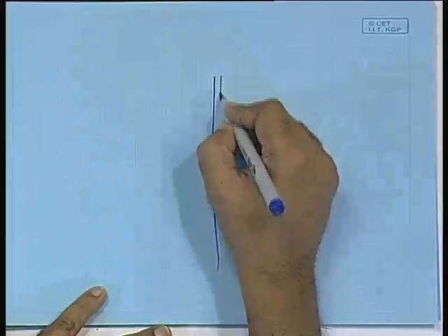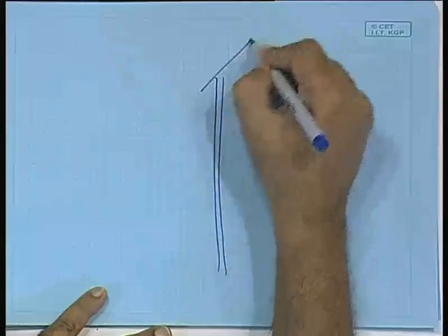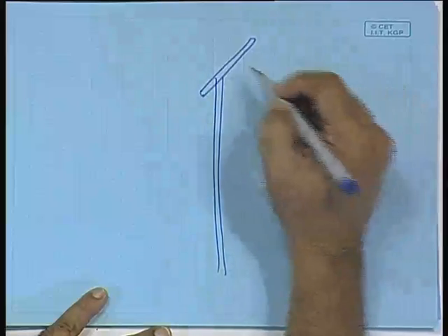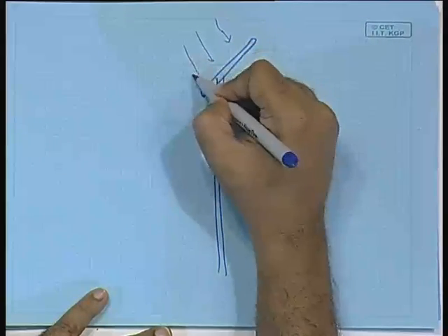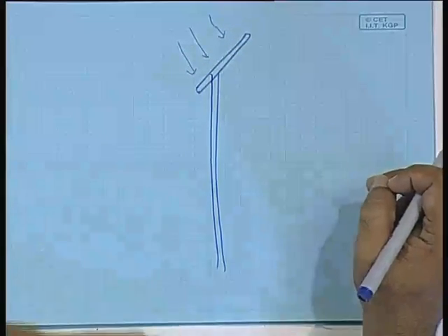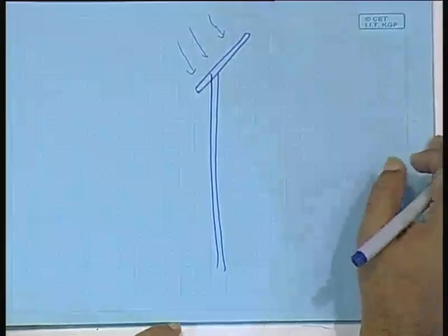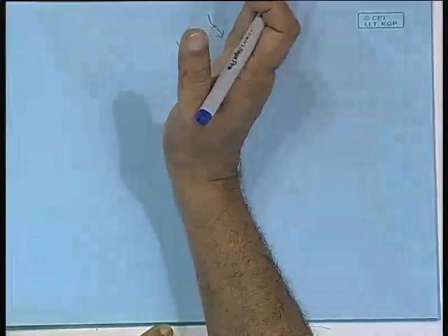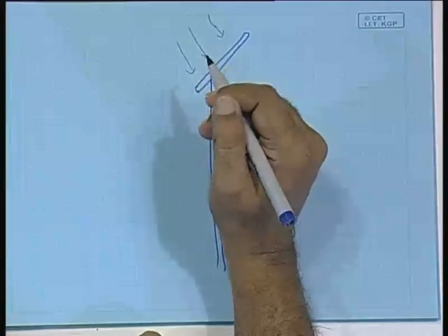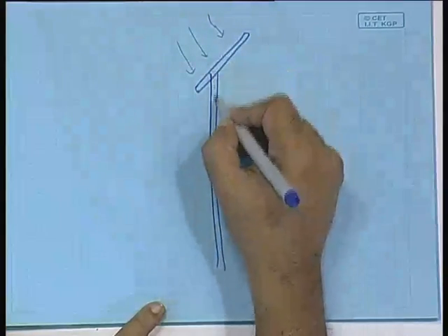One of the things that you might see in some locations is the solar street lighting system. What is this solar street lighting system? You have the pole for the street lighting, and on top of it you have the solar panel like this, which is receiving the sun, inclined at an angle equal to the angle of latitude. Yes, inclined, because this cannot be moved all the time, it is at the top of a pole, and therefore, it has to be inclined at the latitude angle. And then the wire comes down.